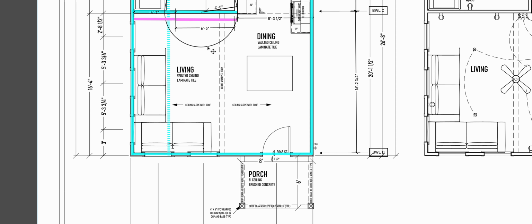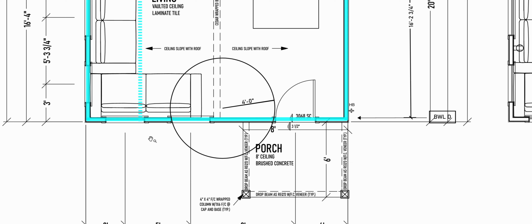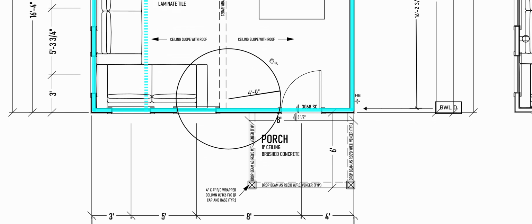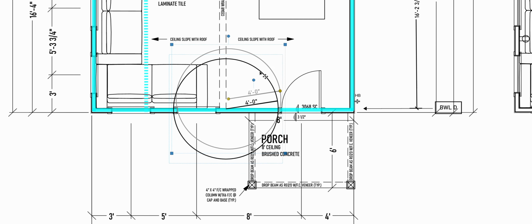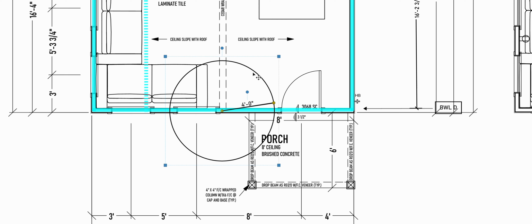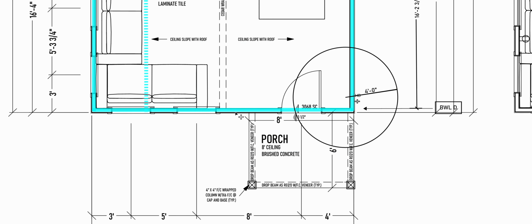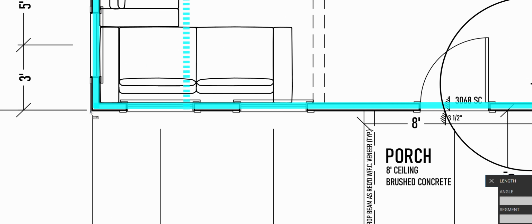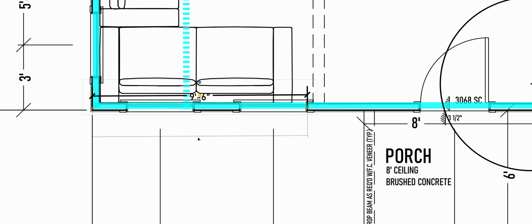Okay, let's go to the front wall. All right, so the front wall is a balloon framed wall. It's a little special, but we're going to treat it the same in terms of meeting the requirements. So the first thing I want to know is, can I get a panel here within 10 feet of this corner so I can not have to do a portal on one of these? Let's find out. 9'6", correct. Good to go.